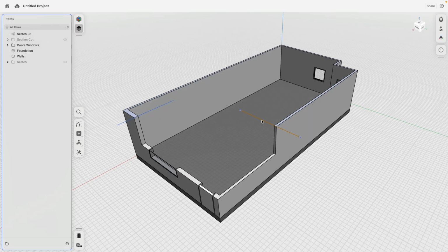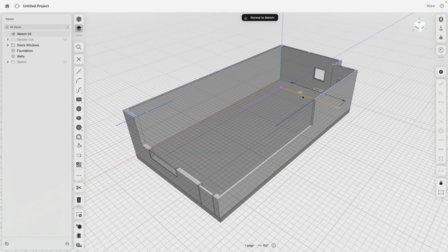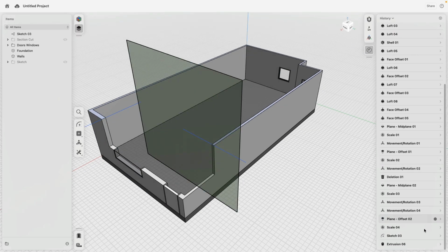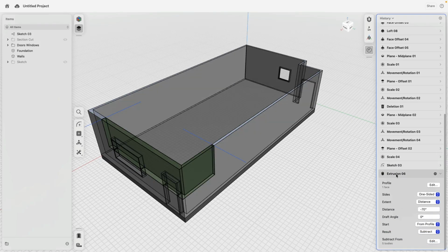Again, if I turn on the sketch with this, I can move this around. It's actually really nice. So you see it gives you a different type of flexibility. And this is all done in this case by using the Boolean command, the extrusion command. And when the extrusion command realizes it is going through other objects, it will turn into the subtract mode and cuts.